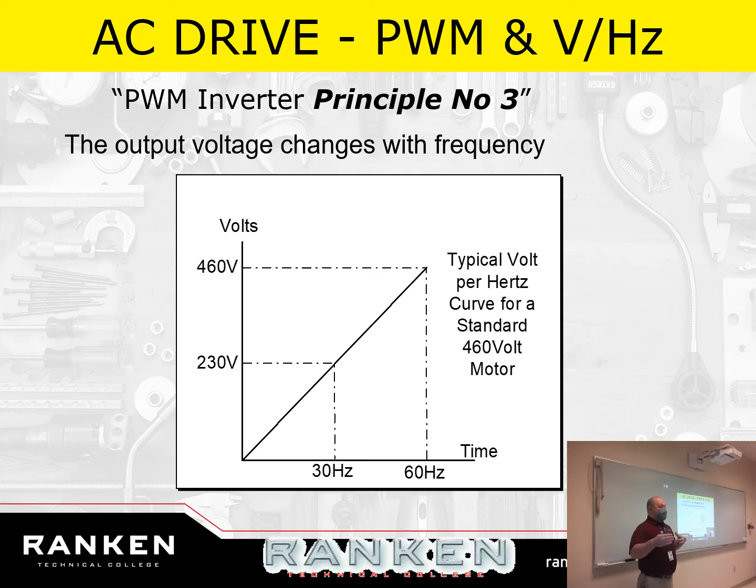If you don't get what you expect to see, if you don't get infinite and zero, you have a bad transistor. Okay? And you can check both of these IGBTs by going positive to T1 and negative to T1. Both polarities. Alright?